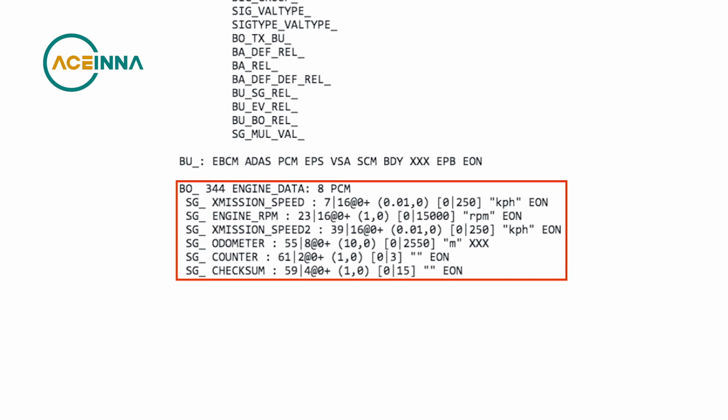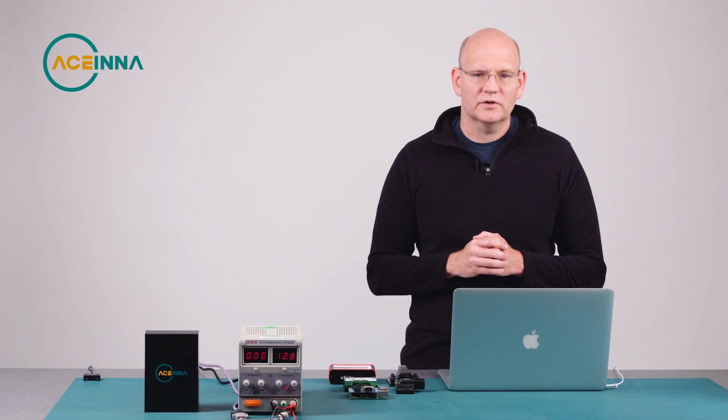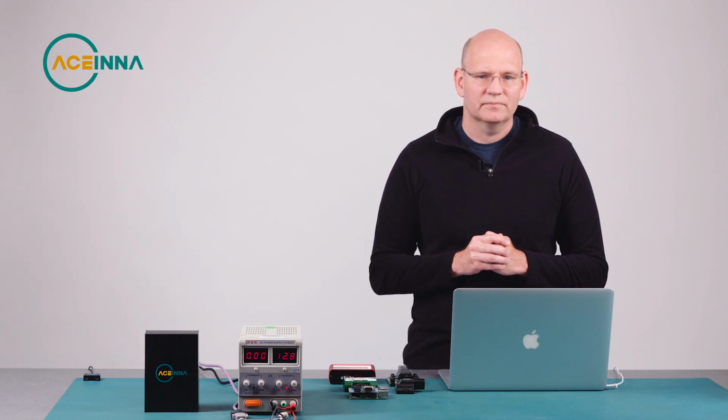The message is 8 bytes, which is the max payload length of a CAN 2.0 message. The encoding of the 8 bytes is shown bit by bit in the next section. This is literally the decoder ring that converts the raw bits to engineering units.